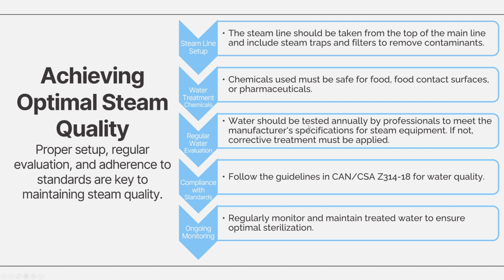Regular water evaluation. So at least once a year, water quality should be professionally tested to ensure it meets the manufacturer's specifications. If there are any tests that show impurities or imbalances, corrective treatments like filtration or chemical adjustments to the water treatment methods are necessary.